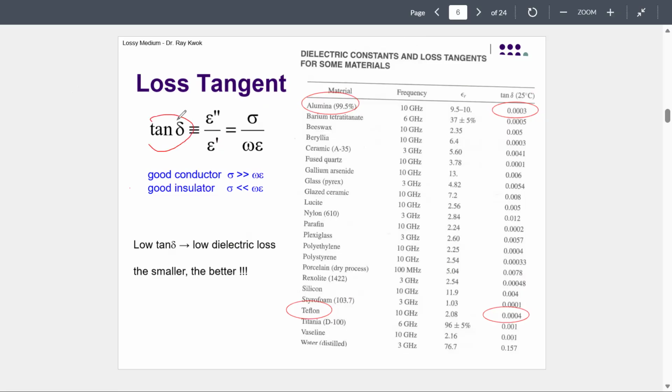We just say loss tangent. The lower the number, the better it is, right? The lower the loss your circuit has. But I have a conductivity here, electrical conductivity. So does that mean a low electric conductivity is lower loss and a good conductivity is worse? Do we contradict ourselves? What do we mean? We can answer that.